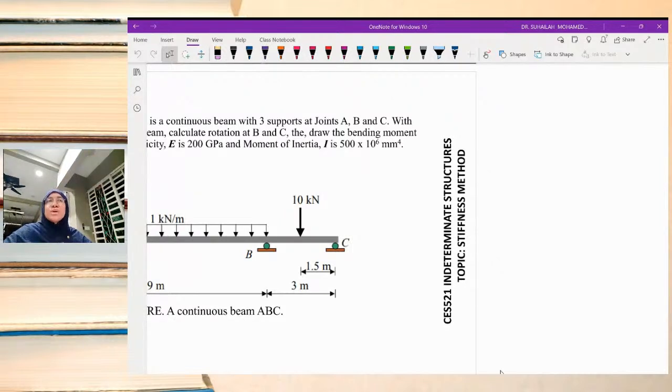We don't have to count the x component because there is no axial force. Axial force in a beam will always be 0 for the horizontal force, so the axial deformation can be neglected.